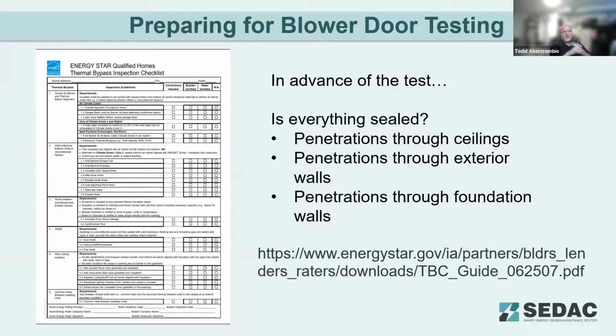How are the ceilings going to be air sealed, so there's a separation between attic spaces above those ceilings and not? Because if you do a blower door test and fail, and you're at drywall stage and all the insulation's installed and there are problems, nobody wants to go through the attic and swim through all that fibrous insulation to try to seal something. So having that plan in place at the beginning is critical.